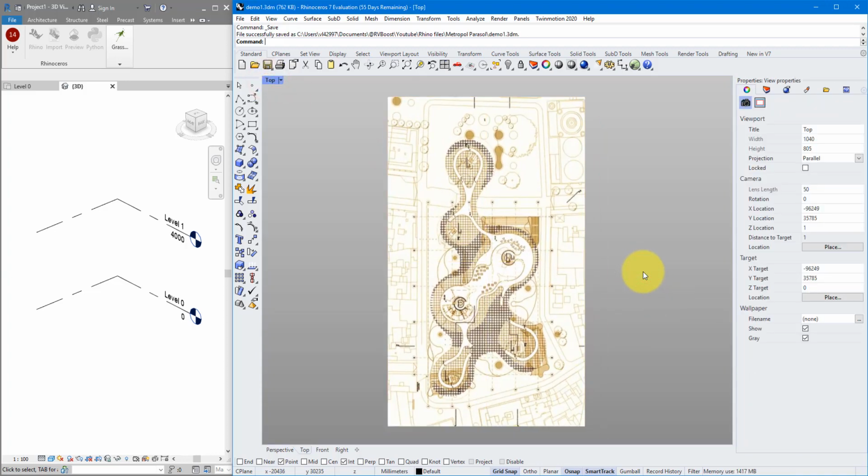Let's begin by drawing individual surfaces that our individual columns will support. So we have here 1, 2, 3, 4, 5, 6 of them. Actually, you know what? Before doing so, I will make sure that this distance from here to here is actually 170 meters. Let's draw a circle now to verify this. So, radius 170,000.